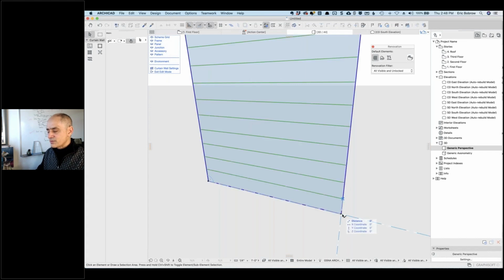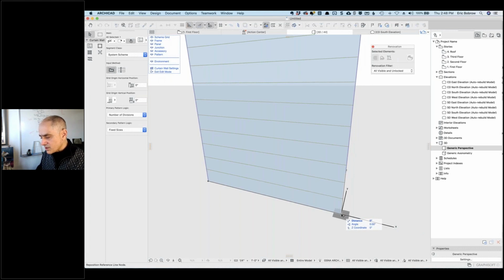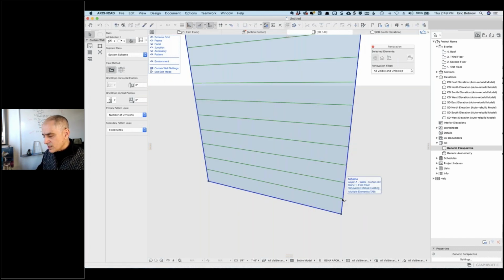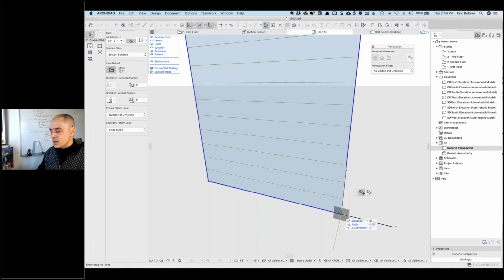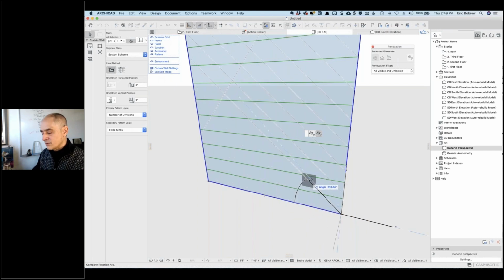Now, if I select this, so it was visible, but now I've selected it and I press down on a corner. I think, actually I have to go, maybe I press down on here. That's the scheme. Okay, I don't know. For some reason, sometimes it comes up and sometimes it doesn't. This says I can move the grid, so I could have it start at a different elevation or a different point horizontally, but this is rotate. So I'll say rotate the grid. It says enter rotation center point. I'll say it's going to start here. It's currently here, and I'll take this up at 45.